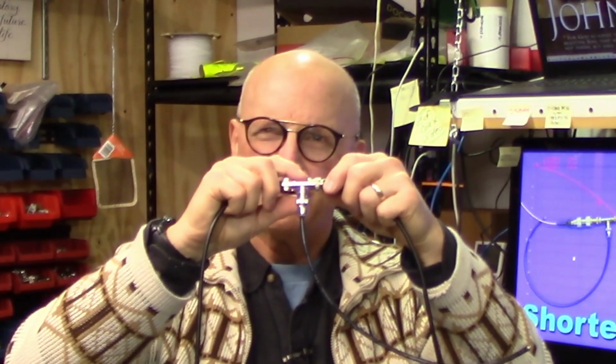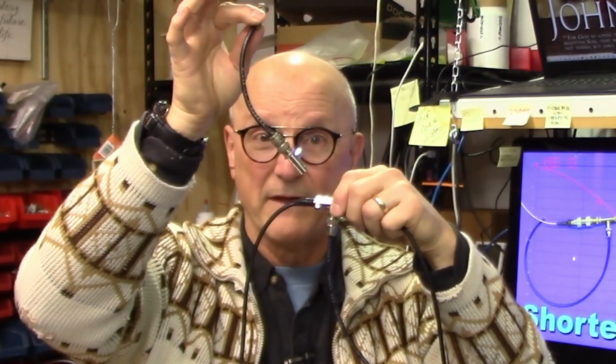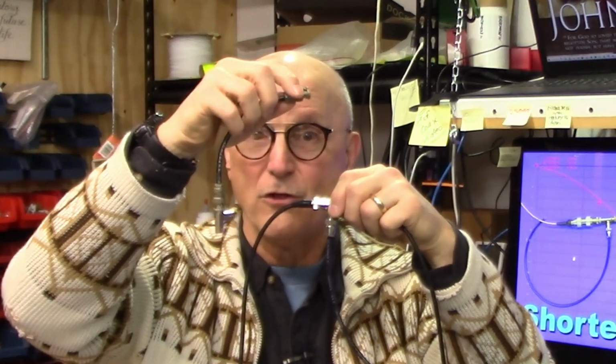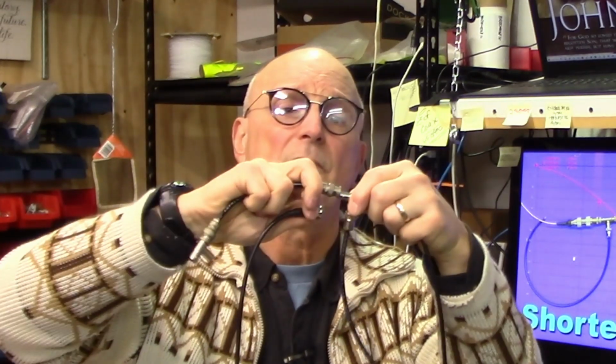Continuing with our transmission line impedance transformation realities, if we have a short at one end of our coax, then we will see a very high impedance at the far end of a 1/4 wavelength long piece of coax. With this in mind, let's think about it for a moment. The impedance at the T connector is low, nearly a short at the desired frequency. What if we inserted a piece of coax between this T and another T connector that was 1/4 wavelength long at the frequency in question?